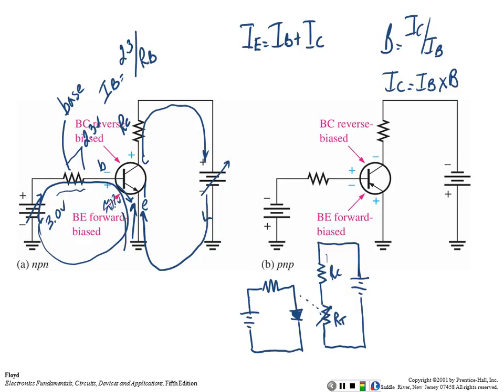With FETs, we control the size of the valve with a lead we call a gate, but they work exactly the same. Transistors are current valves. We control it with one lead, and we're going to control the current flow between two leads.